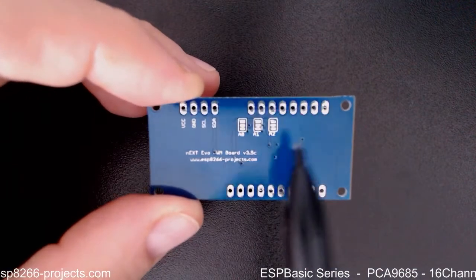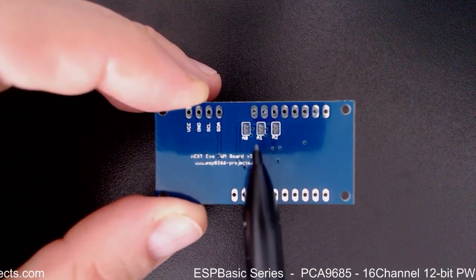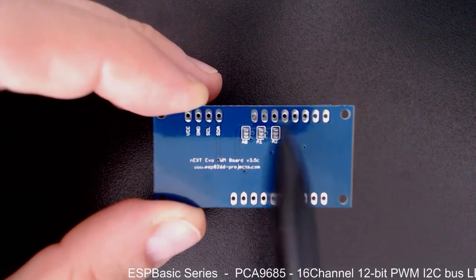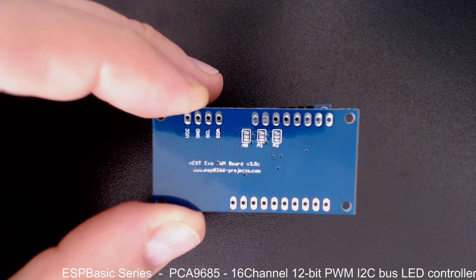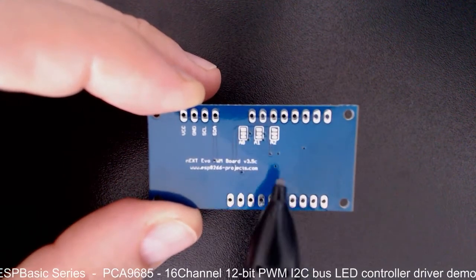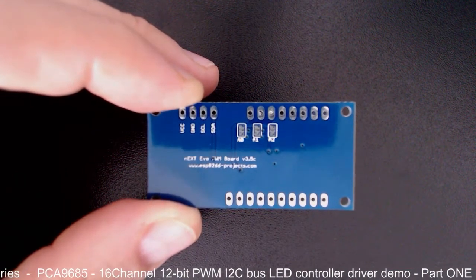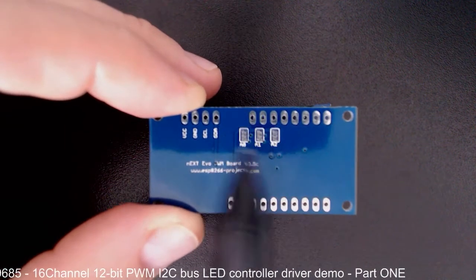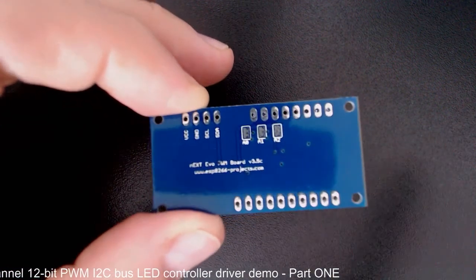On the back of the board we also have 3 jumpers from where you can select your I2C bus address. So with these 3 jumpers, basically you can change the I2C address for the PCA9685. The default I2C address is 40 hex, that means 64 decimal. But you can change it from here to avoid interference with other I2C bus devices that you already have, and they might be on 40 hex.